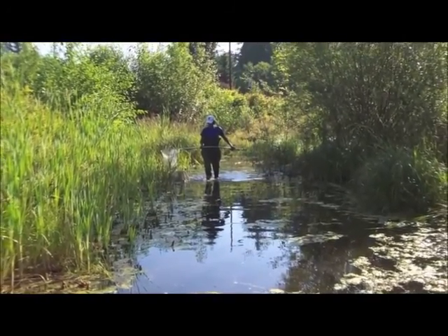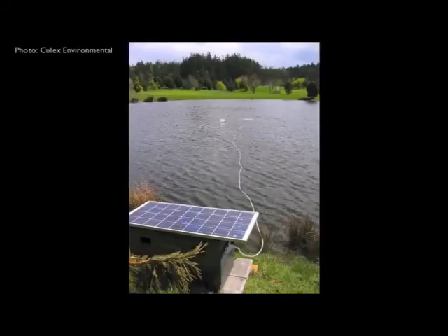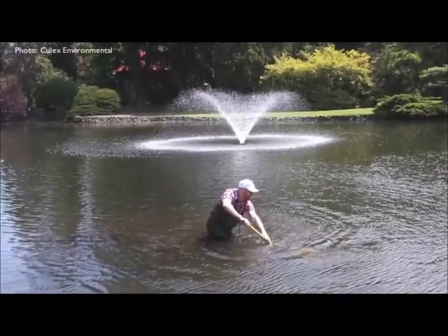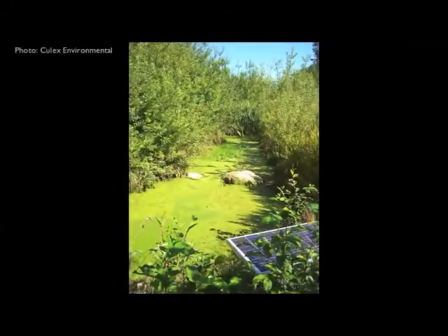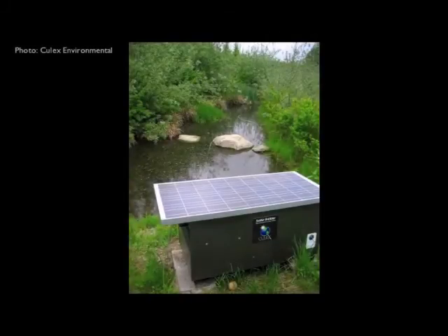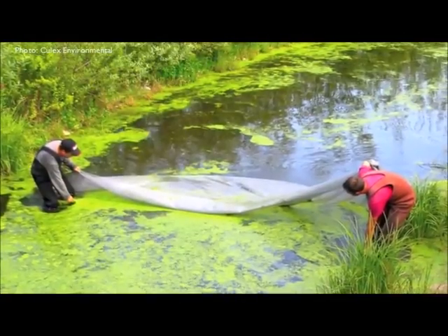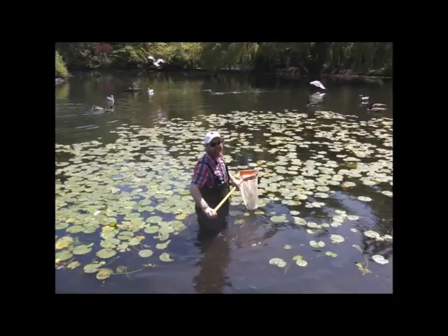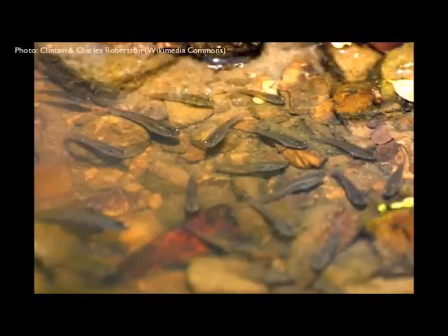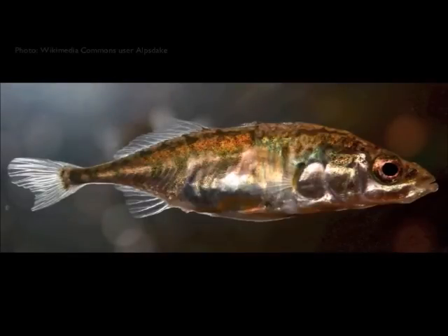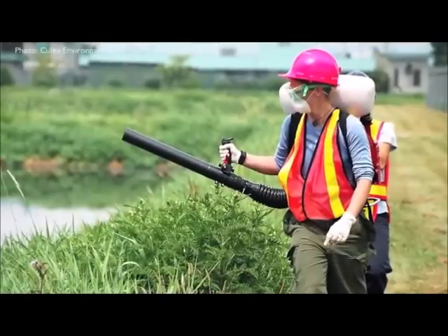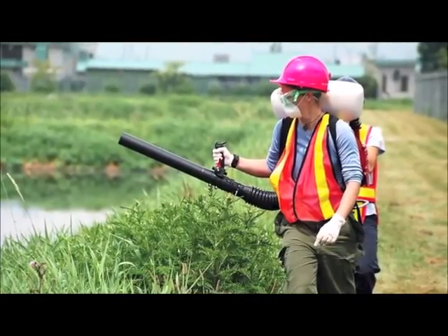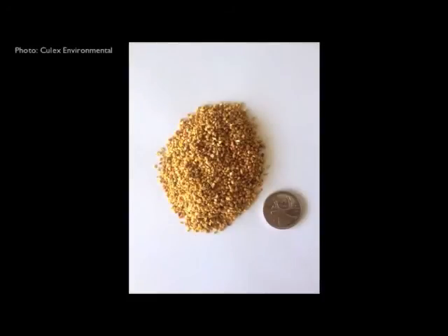We can decrease mosquito problems by minimizing stagnant water bodies by installing an aerator or fountain in the wetland, minimizing eutrophication and resulting algal blooms, as the algae provide food for and protect mosquito larvae, planting water lilies to cover the water surface, thus preventing larvae from connecting their breathing siphons to the air above. With proper permits, introducing predators that eat mosquito larvae and can survive semi-contaminated conditions, such as sticklebacks. And as a final resort, adding a biological control agent, such as a bacterial larvicide, to the wetland.